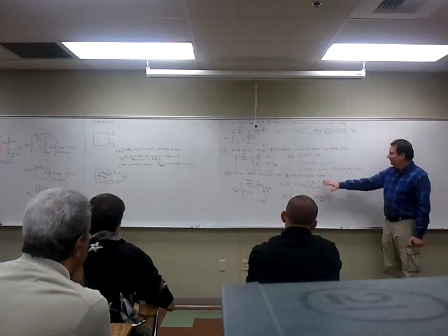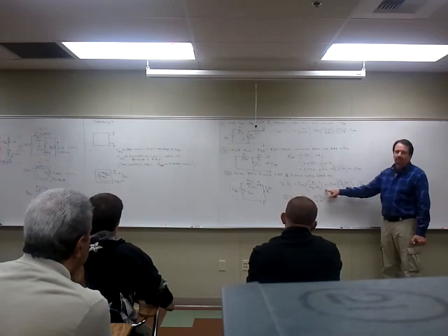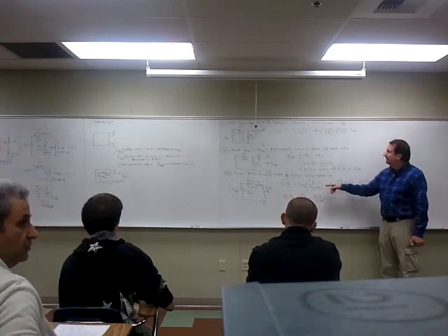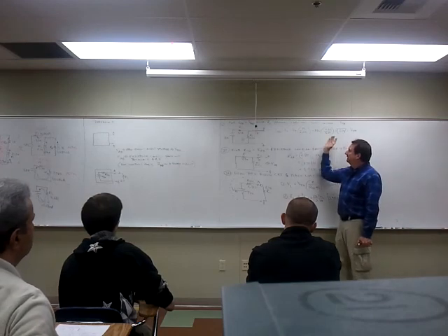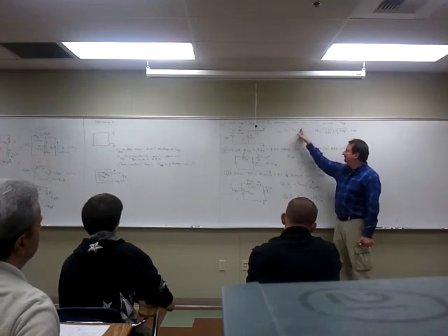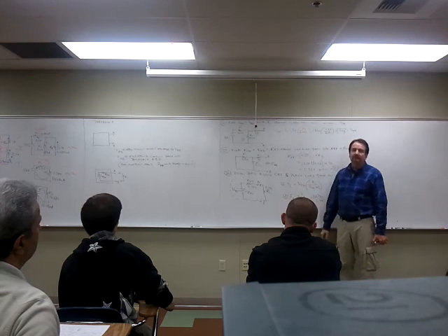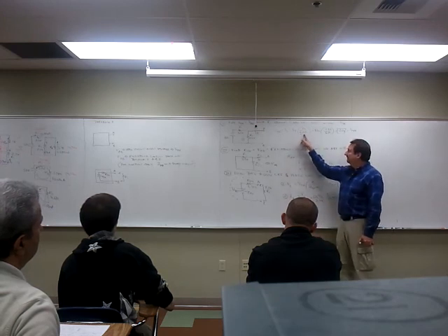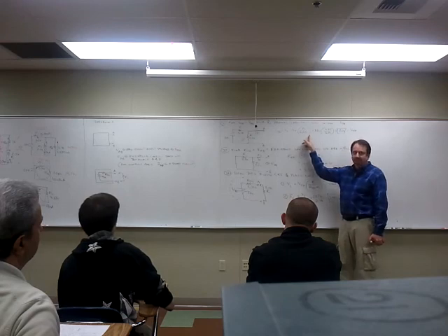No, there's no voltage. There's a voltage divider down here. I'm saying, the way that it's written out right now, that's the way it stays. You mean steps going this way? Yeah. Well, it's the total voltage times the ratio of the resistor you're looking at over the sum of the resistors. Yes, that never changes. If it's 3 resistors in series, it'd be 3 resistors added up.